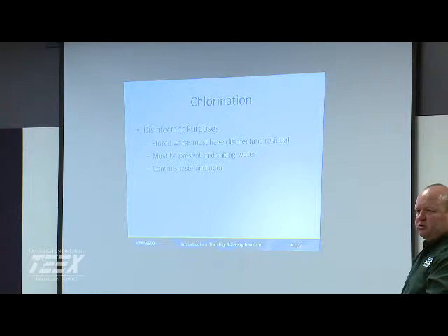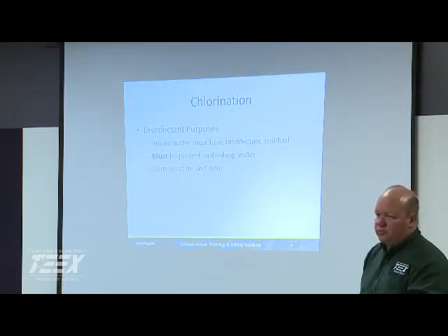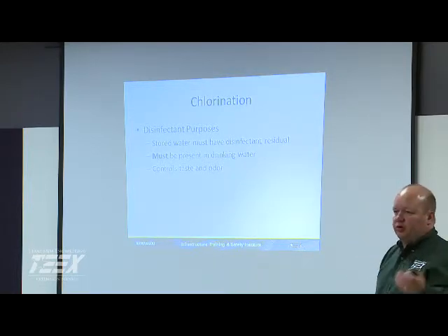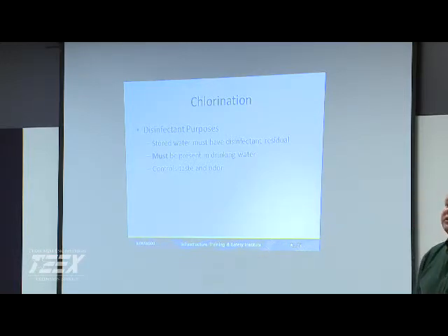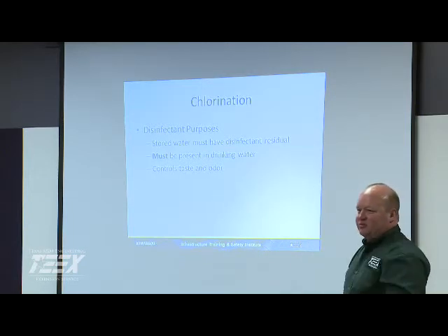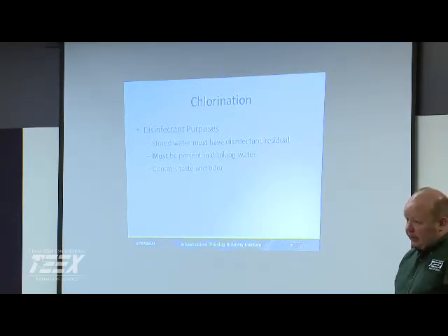How much are y'all using? We used to be at about half a part or something of it. Well, I think it's up to 0.7 now is what they've recommended us feeding. We actually went from a saturator that we couldn't really control well to just the bulk. Well, it's not a bulk tank, but a tank where we can measure water per dosage of chemical. Do you have a silo that you're dumping it into, or where do you get your powder? You would just get the little 55-pound pails or something. Okay. Well, that might be a little easier to control than having a big silo where you've got shakers. It's not that bad, it's just messy, it makes a mess everywhere it's at.